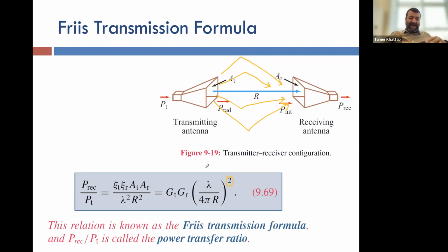That's a random value added to this path loss. But that is a different analysis. Here we are only looking at, as you go away from the transmitter, how much of your power is lost, right? So it's only a distance dependent analysis, this one. Of course, in addition to types of antennas that you use and wavelength and so on, but the main characteristic here is as you go away, as you increase the distance between the transmitter and the receiver, how much you lose in terms of power on the average. This is a long-term average, okay?